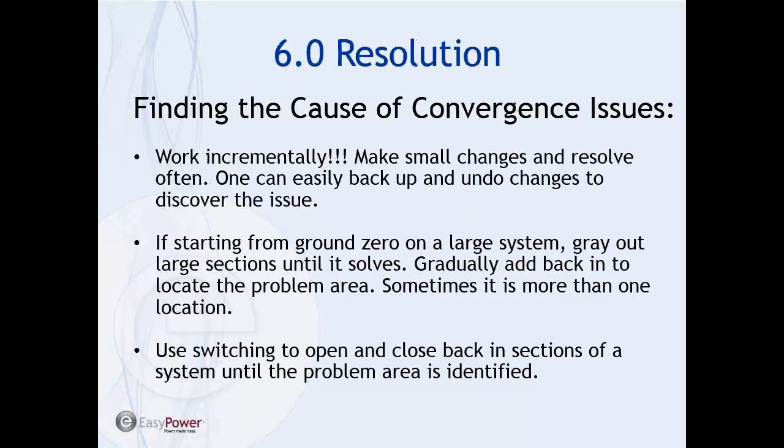Now, how do we find the cause of convergence issues? Work incrementally. I'm going to say it again. Work incrementally. Make small changes and resolve often. One can easily back up and undo those changes to discover the issue.